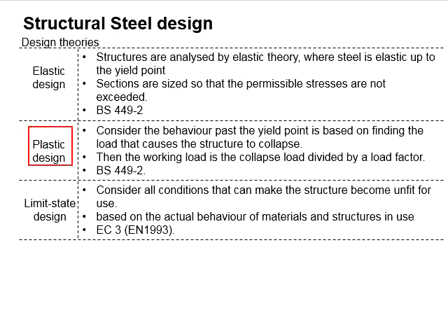As for the plastic design, it considers the behavior past the yield point, which is based on the findings of the load that caused the structures to collapse. The working load will be the collapse load divided by a load factor. This is also in accordance with BS 449.